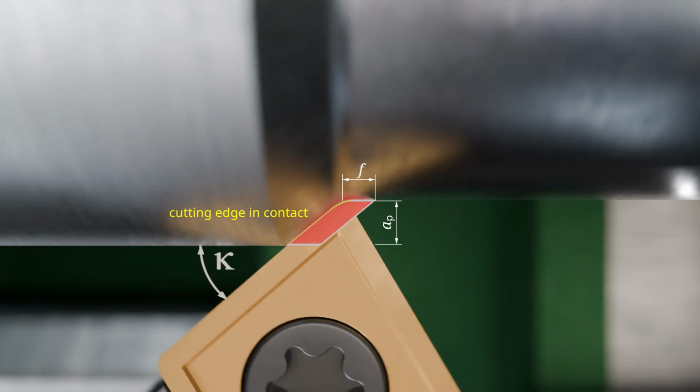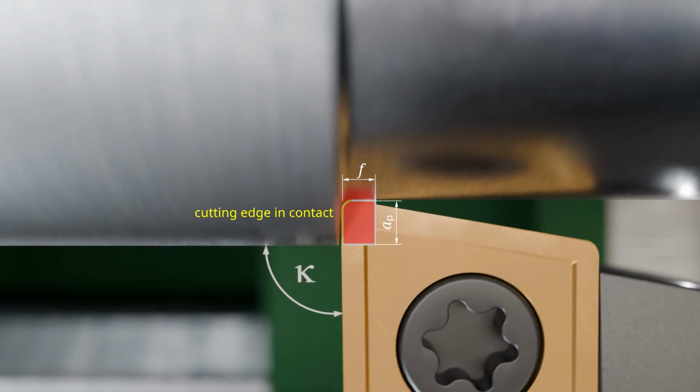Conversely, with a large approach angle, the chip is relatively thick at the same feed rate and depth of cut, and the cutting edge load increases because only a small part of the cutting edge is engaged, and the cutting forces cannot distribute as well. The short cutting edge length also reduces heat dissipation, which thermally stresses the cutting edge and leads to increased wear.